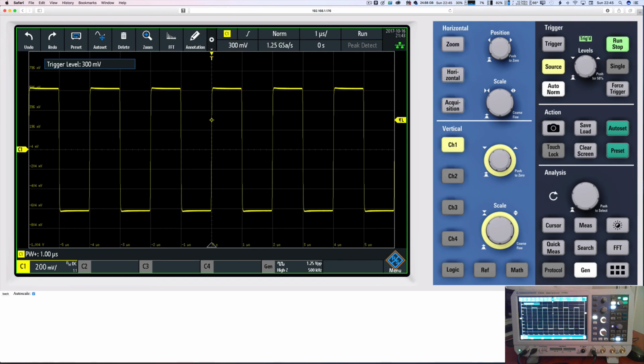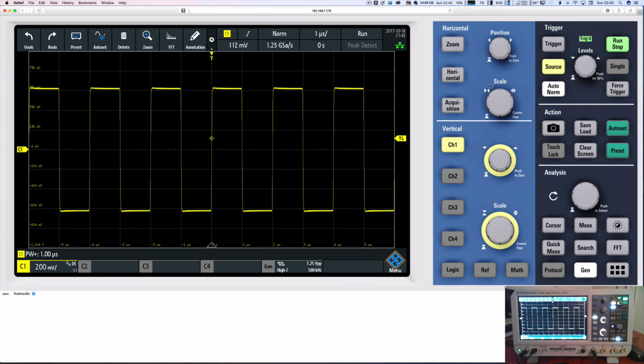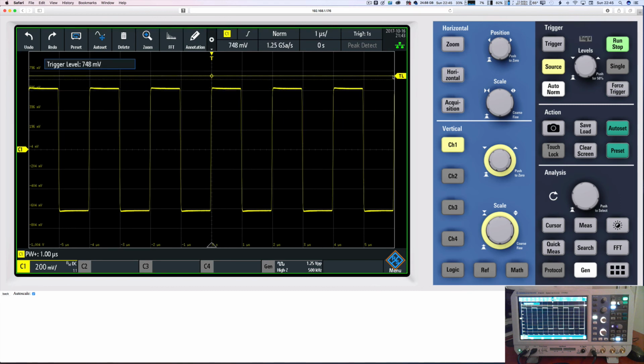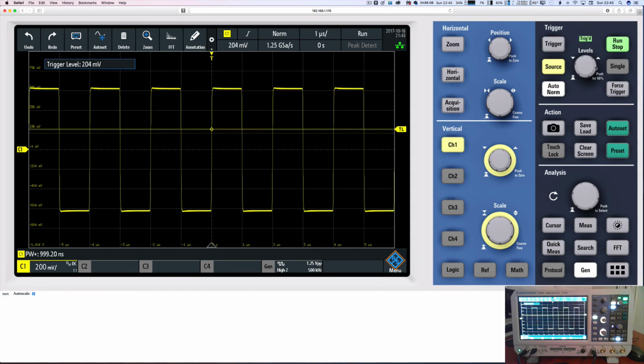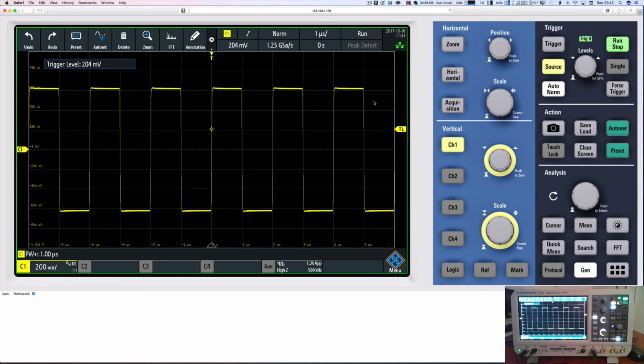So that was correct. I suddenly thought they'd written that wrongly, but in actual fact, on normal, it remembers your last trigger when you remove your trigger level above your signal to untrigger it effectively, which is quite nice. And obviously you've got a trigger light here, so if I move this up here, it's not going to show me that it's triggered, but it still remembers my last one. Clear the screen so we won't see that. So the trigger is off. If you watch that trigger light, as I pull that down, the trigger light shows that we're triggered now, which is quite useful.